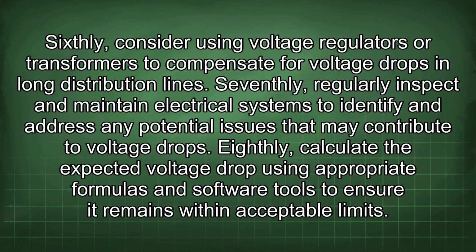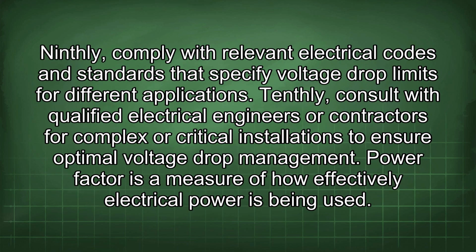Eighthly, calculate the expected voltage drop using appropriate formulas and software tools to ensure it remains within acceptable limits. Ninthly, comply with relevant electrical codes and standards that specify voltage drop limits for different applications. Tenthly, consult with qualified electrical engineers or contractors for complex or critical installations to ensure optimal voltage drop management.